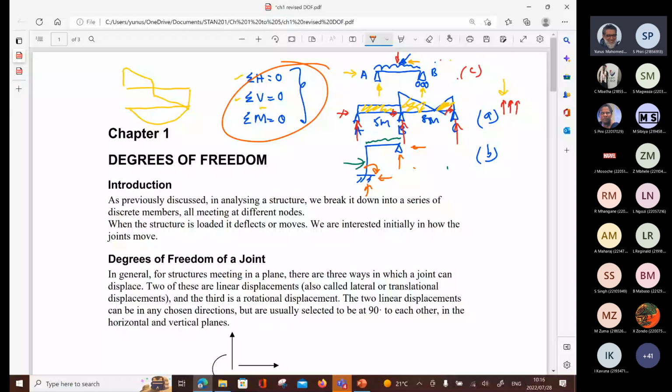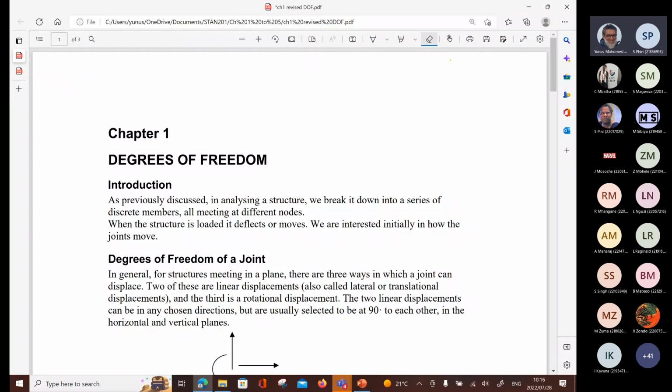Okay, we had the one span beam with the pin and a roller, statically determinate. Reason: reactions are 3, 2, 1 vertical, 1 horizontal on the left, and 1 vertical on the right-hand side. So 3 unknown reactions. I have 3 equations, solve, no problem.